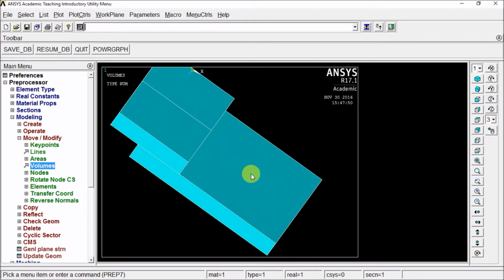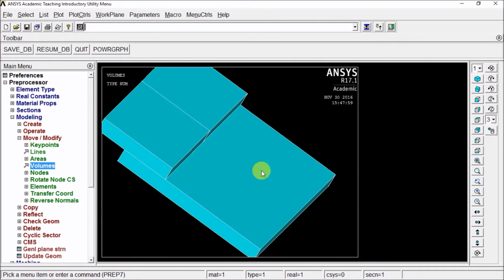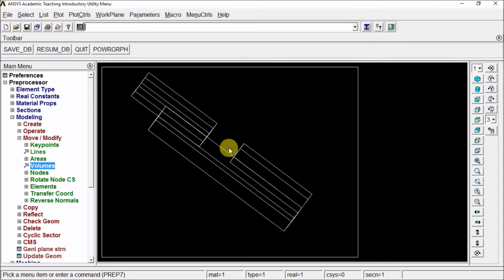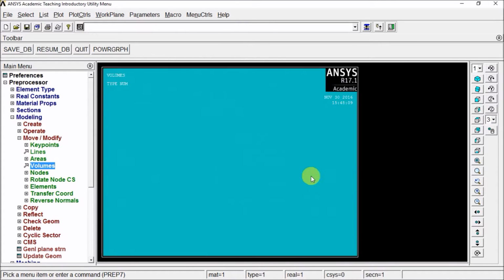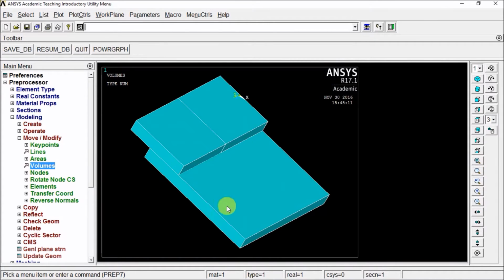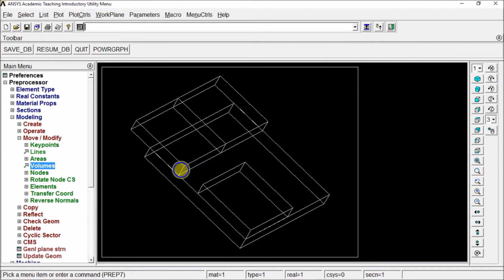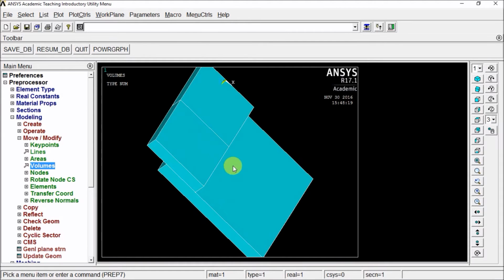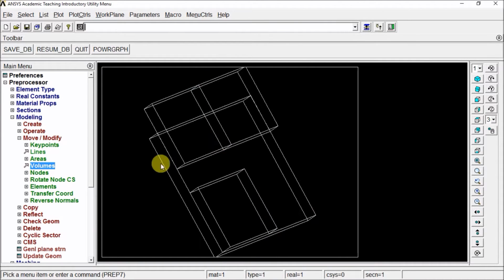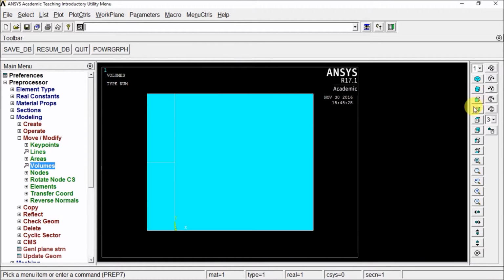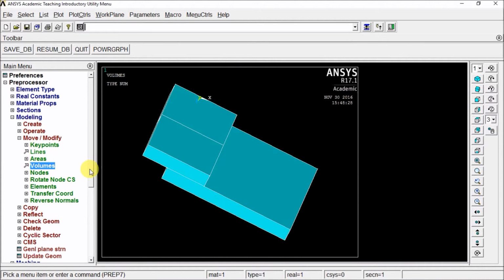Remember, with making contact pairs, ideally only the surfaces that are touching will have a contact pair between them. Obviously on the top of this plate I've only got one big surface, so I'm going to have to do a contact pair between this whole surface and the bottom of this block. Ideally there'd be maybe 4 different surfaces that make up the top of this plate, and I would do this surface over here connected to the bottom of this block and so forth. But that's not what I have right now, so I'm just going to do the best with what I have.